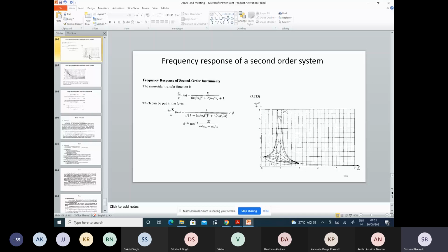If you think about the first order system, if you have a single pole, your plot comes and then goes down at minus 20 dB per decade, and near the corner frequency it is a little bit damped. If you have two real poles at the corner frequency, not complex conjugate, you will get a minus 40 dB per decade slope from the corner frequency, and that is a little bit lower than the asymptotic plots.